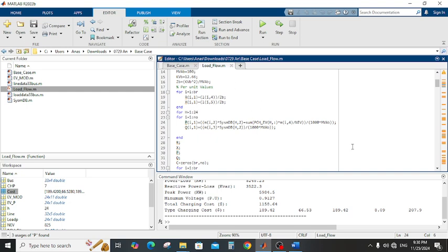But a very important command here. This is the very important command. It is the nominal real power of the system multiplied by the system load profile, plus the sum over the whole types of EV multiplied by the number of EV at that bus divided by the total number of EV in the system. This is the important equation that we calculated here.